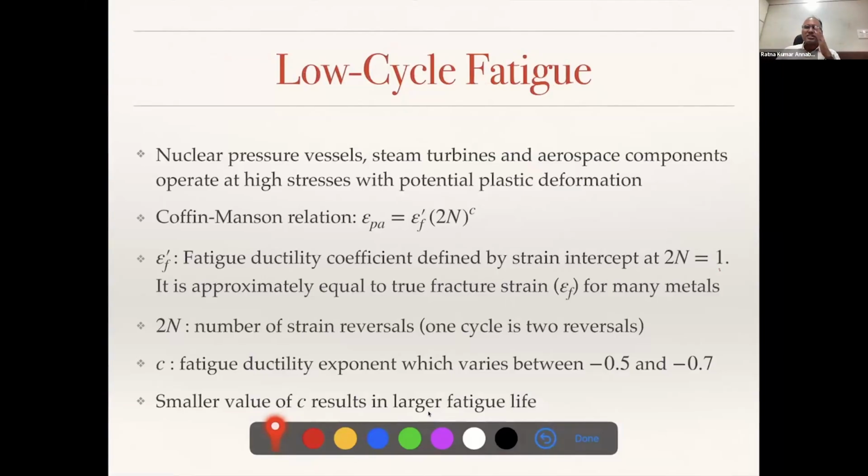Now, what did we understand until now? Whenever you are doing cyclic loading under plastic deformation, because when it is elastic deformation, no problem, the path traced is the same. The problem comes only when you have plastic deformation. Under plastic deformation, if you are doing the stress reversal or strain reversal, the plastic deformation is going to happen at different points in tension and compression, right? And now you are operating between a certain strain range.